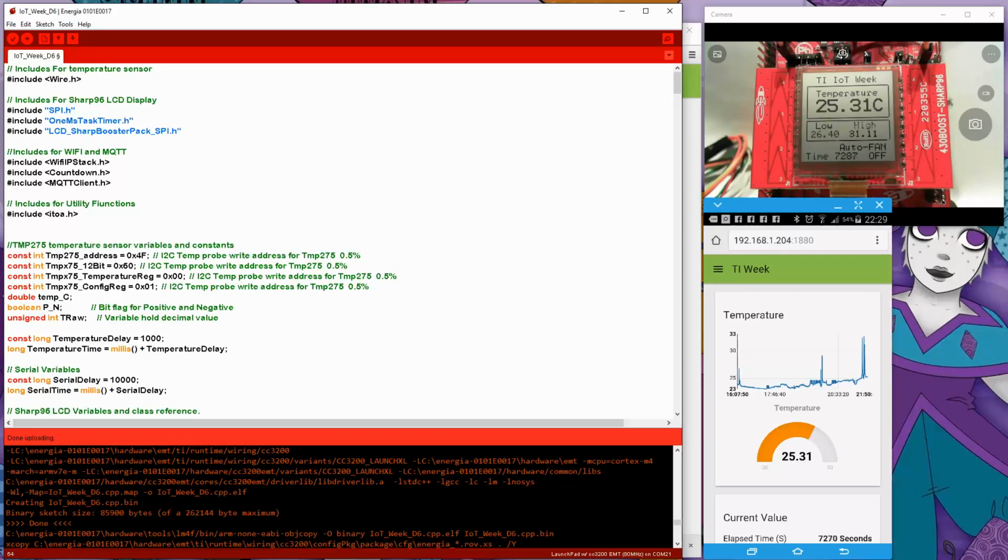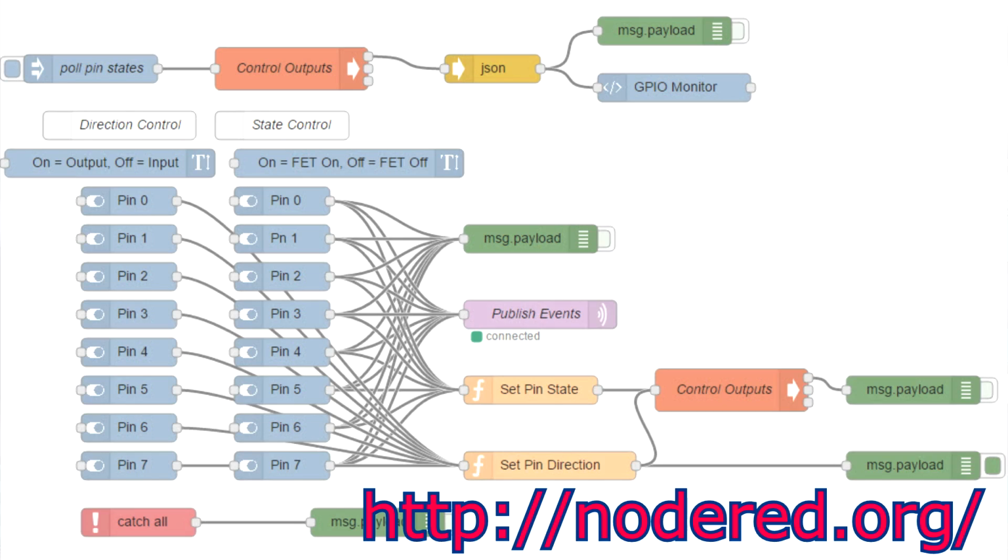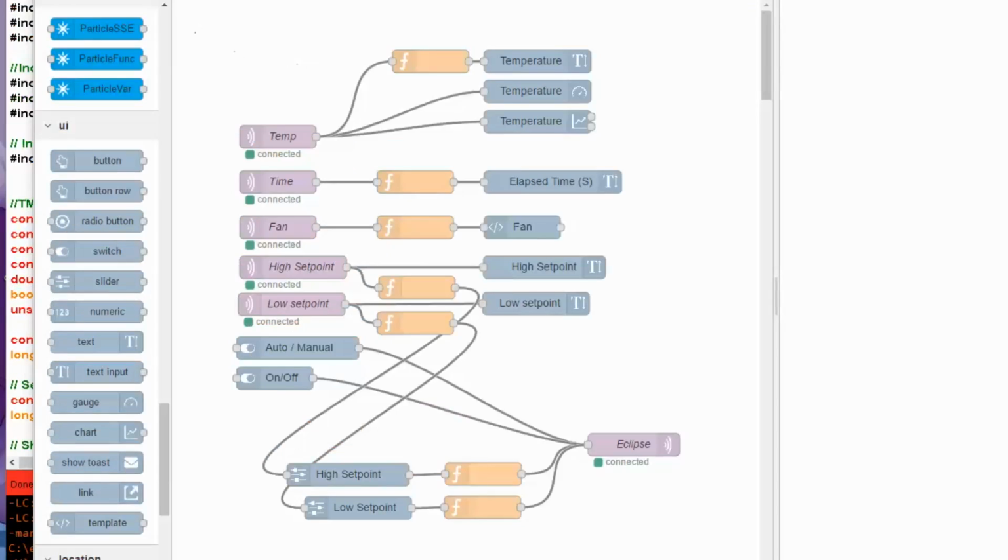What it is, is an application that allows you to graphically design a process control. It's designed for laying out a flow, a little bit like a PLC control. So this is the instance of Node-RED that's running under Debian Jessie, on the Sitara processor on a Mica control unit that I have. When Node-RED comes up, you've got an administration screen here, which is where you can design your workflows.